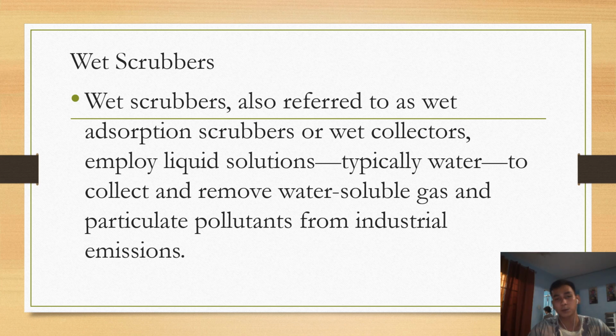The wet scrubbing process either passes a gas stream through a liquid solution or injects a liquid solution into a gas stream. As the gas stream comes into contact with the liquid, the solution absorbs the pollutant, removing it from the stream. The types of wet scrubbing equipment available include venturi, packed bed or packed tower, and bubbling scrubbers.